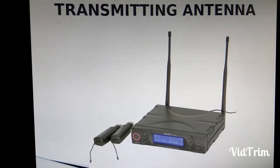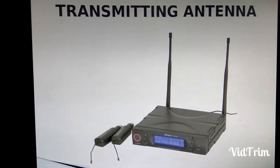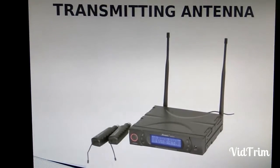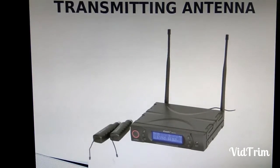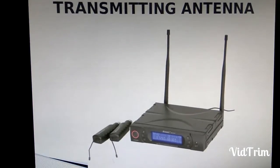In transmission, a radio transmitter supplies an electric current oscillating at radio frequency, that is a high frequency alternating current, to the antenna's terminals, and the antenna radiates the energy from the current as electromagnetic waves, that is the radio waves. In reception, an antenna intercepts some of the power of an electromagnetic wave in order to produce a tiny voltage across its terminals that is applied to a receiver and is finally amplified.